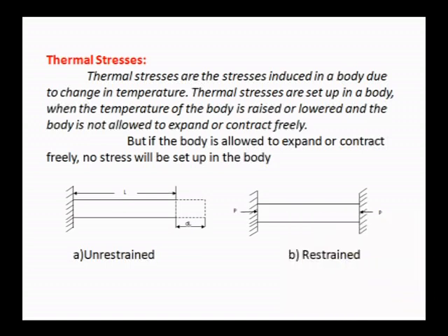Here I have given the two conditions, unrestrained and restrained. Unrestrained means one end is fixed and the other end is free. Due to the free end, it undergoes changes; it undergoes elongation due to the rise in temperature.